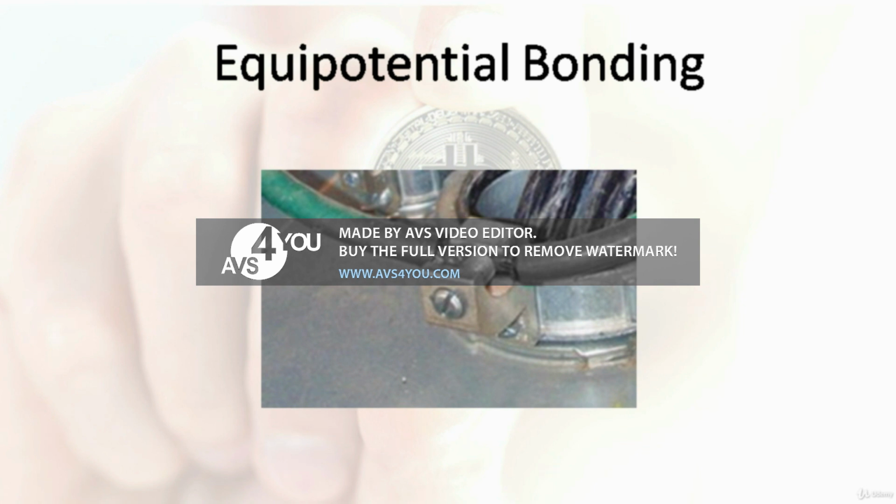Bonding should not only be connecting the equipment, but also service pipes, ducting, heating, and air conditioning systems. You connect all of these components through something called a bonding conductor, the size of which will depend on the anticipated fault current your facility might have.